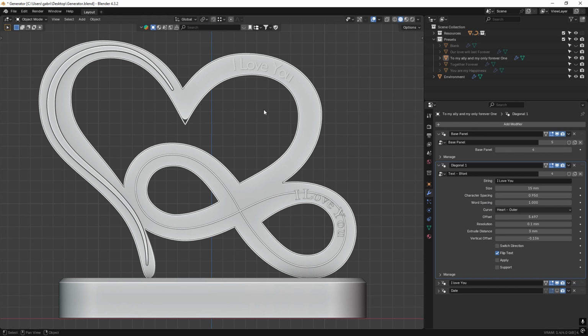One important thing, I put here the character spacing to allow you to change the spacing between characters, not only for aesthetic reasons, but also for technical reasons. You should avoid character collision. So in this situation, the O and the U are colliding, so you should increase the character spacing at least to 1 to avoid the collision, or maybe you can put it also to 1.1. Okay, so avoid character collision because it will cause some issue.